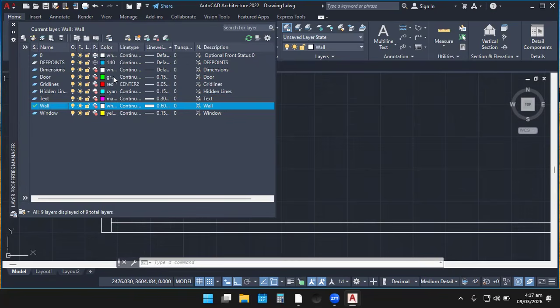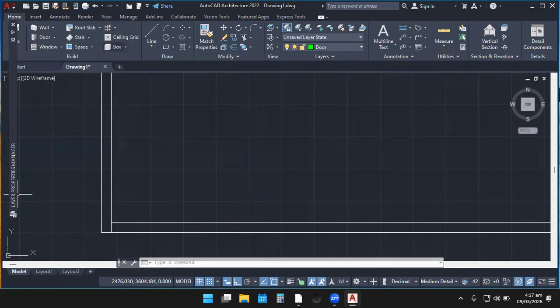This is the door over here. So I'm going to select the door. Then I set it as the current layer. You see, set current layer. Exactly. So I can just hide it again and continue my drawing, so that the door has been set as our current layer. And so I'm going to offset this line. So I click offset, then I select this line.